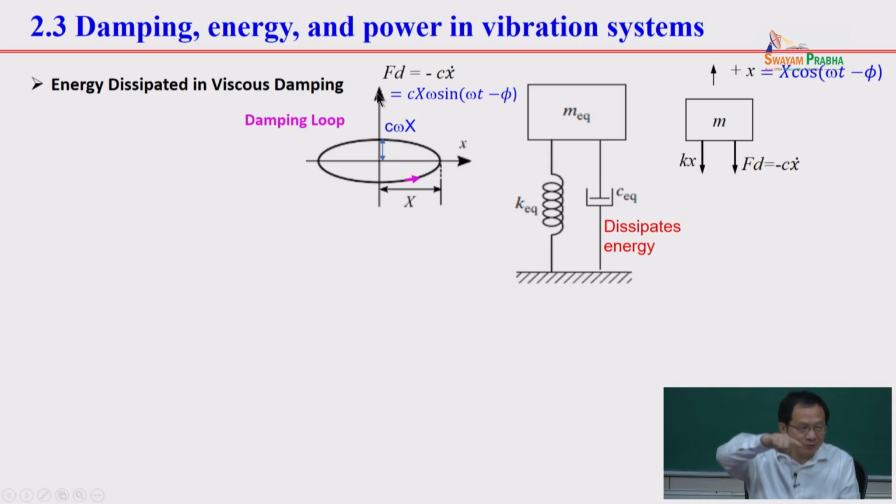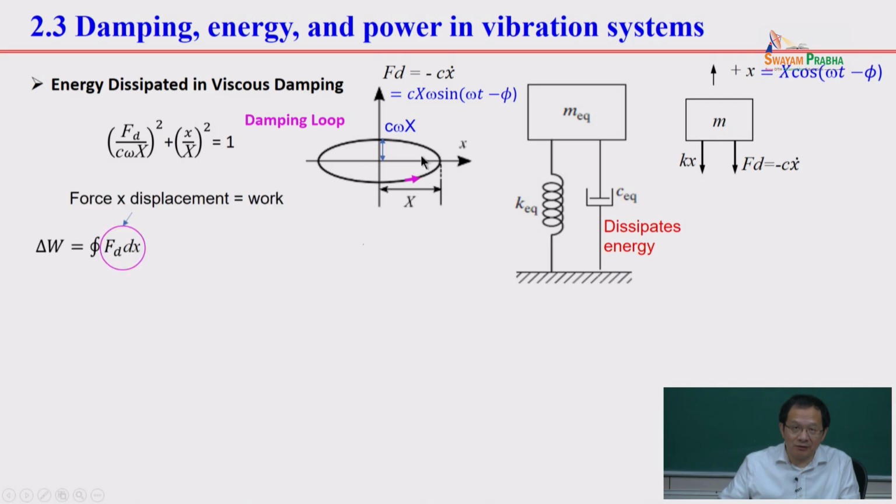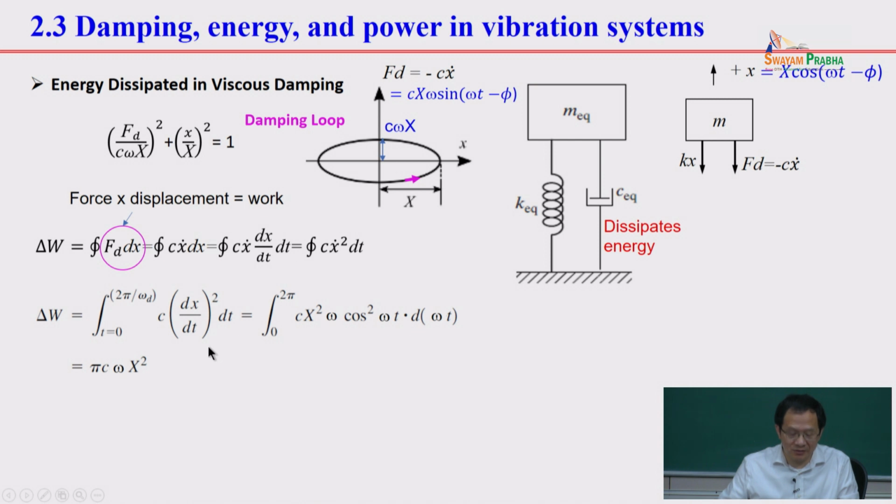Force displacement is just one line, right? If you have a spring, the force displaces along one line, and that means you get energy stored and get energy back. Now for this damper system, you go through one cycle, and the area under the loop is the energy. You integrate the loop, force times displacement. This area is the energy.